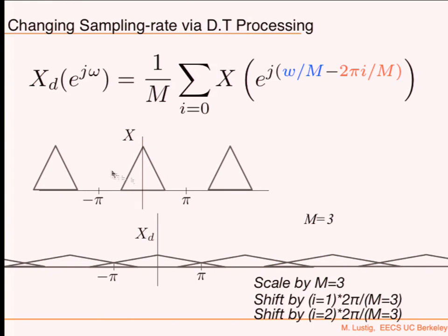If I downsample this by a factor of 3, there's no way I can represent everything. It's like originally I would have sampled at a 3 times lower rate. Of course, it doesn't fit the bandwidth. So remember how it would have affected a continuous time signal.